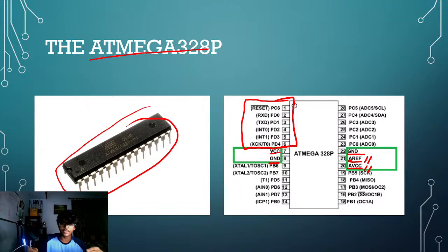So if there are two grounds, you give both grounds the same voltage, and both of them are used in different parts of the IC, and it reduces noise, and it reduces any losses you get from routing it too much around the IC.